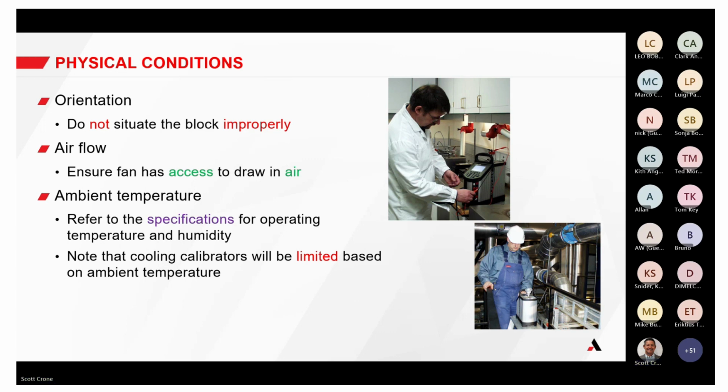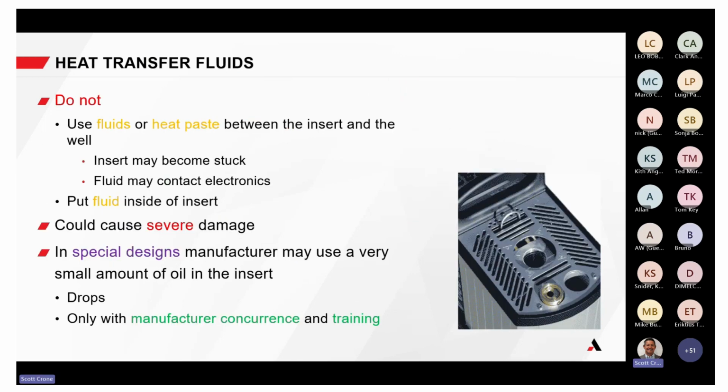Heat transfer fluids. Don't use heat transfer fluids or heat paste between the insert and the well, or between the sensor and the insert. The insert could become stuck. The sensor could become stuck. The heat paste solidifies over time. Not a good idea in there, because then you've got to replace that block. Fluid may contact electronics. Don't put fluid inside of an insert. The only time you want to consider fluid inside of an insert is with manufacturer concurrence and training.